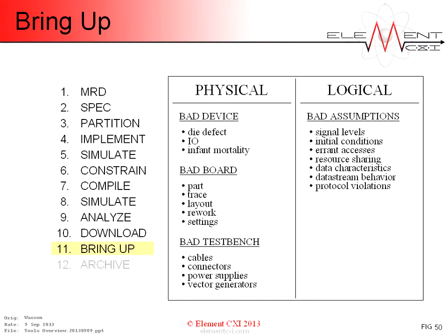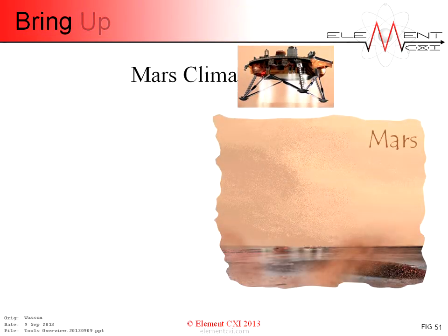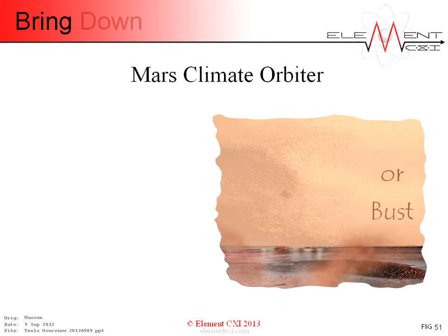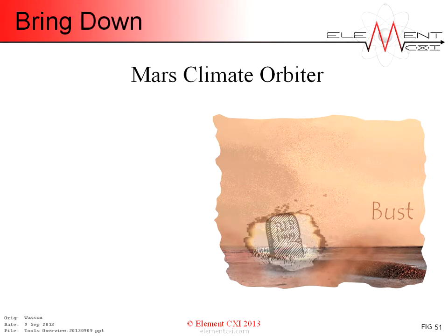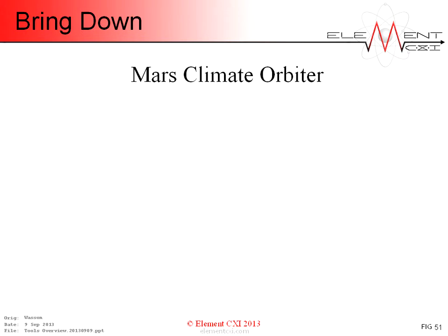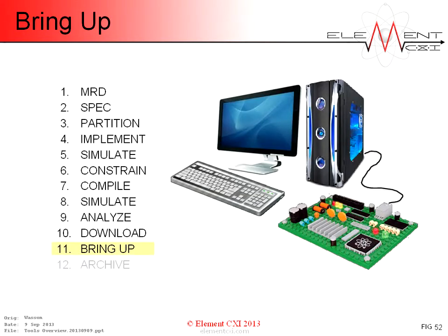For example, with a hand-built embedded logic analyzer, I once uncovered a DMA scatter-gather problem in the Intel Neptune chipset. So, there are lots of reasons for lots of debug support for bring-up, because no designer is perfect. Recall NASA's $125 million Mars Climate Orbiter, which was lost because spacecraft engineers failed to convert from English to metric measurements. Minimally, bring-up tools need to upload static and quasi-static data such as configuration, state, register, and memory contents.